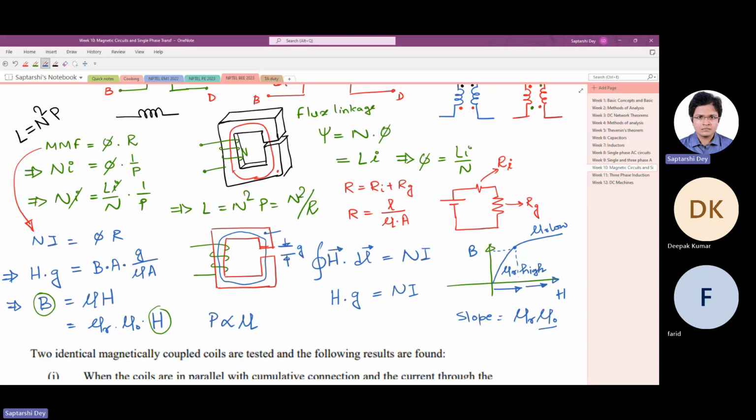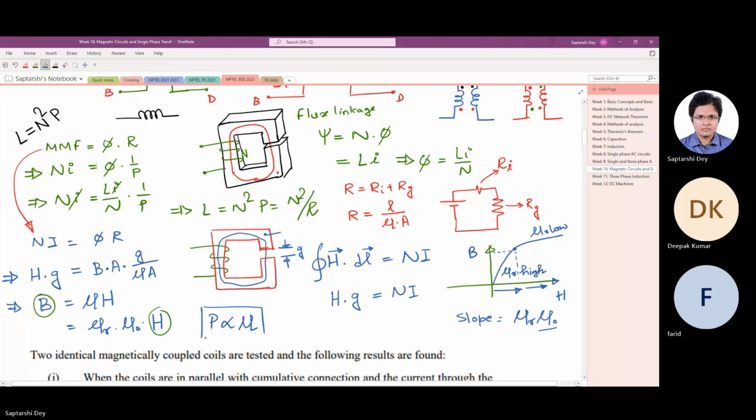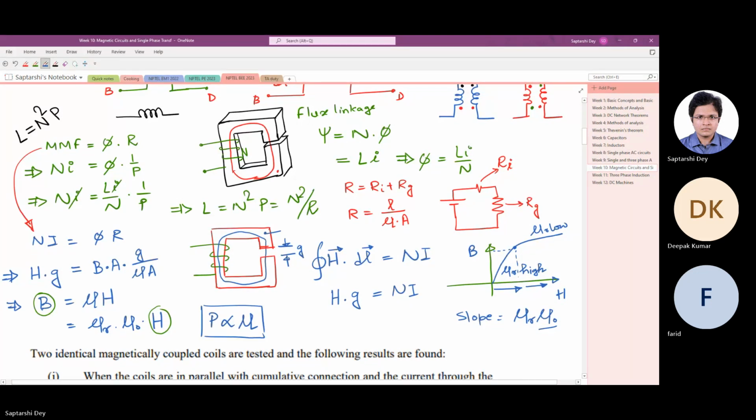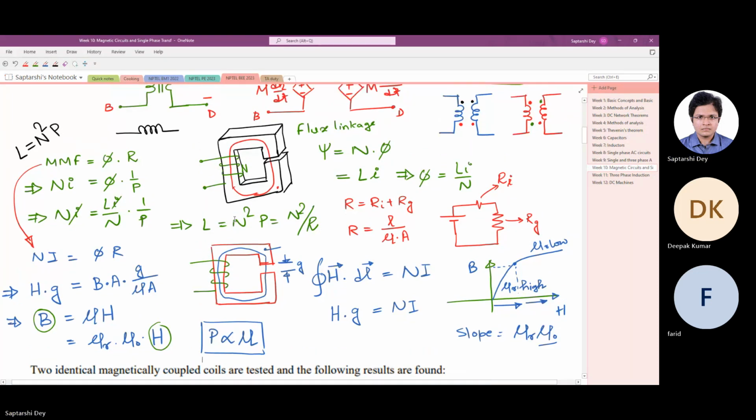It's a nonlinear entity. Although I do not think in this course you have to consider those things, there is something called saturation, and whenever we are designing inductance, we make sure that it is always operating in the linear zone, because we don't want the inductance value to change during the circuit operation. If the current goes beyond its desired limit, the inductance value will drop. So just keep these ideas in your mind, that inductance is not a constant.